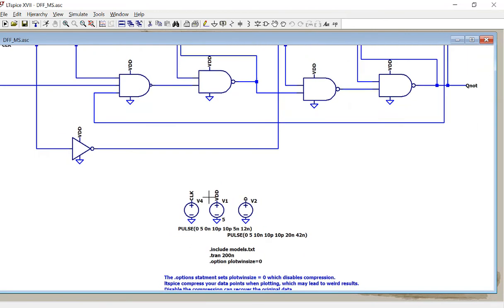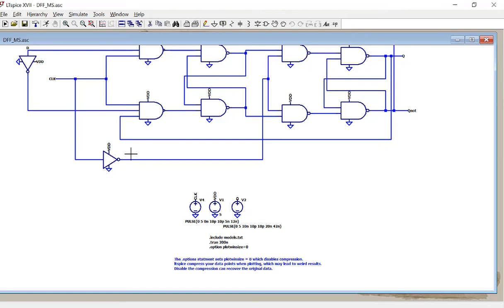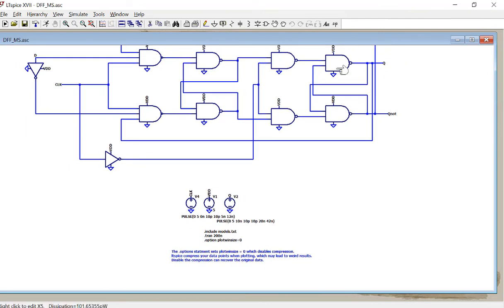And what you need to do is change it to rising edge triggered, right? So you want to put the inverter somewhere else. And second, you want to replace this guy with a 3 input NAND gate and add a set and reset over there and see if that works. You'll probably need multiple simulations. One simulation, verify the logic of the D flip-flop, and then set it, and the third one, reset it. See if that works. All right? Make sense?